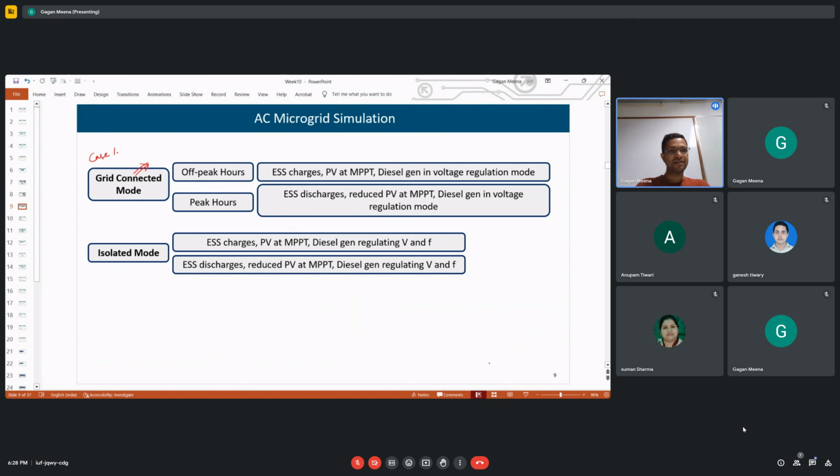Yes. Nice. So DVR, dynamic voltage restorer, D-STATCOM and UPQC. This case study was an example of that UPQC. Here we can see this is one active filter and this is the second active filter. This is the series active filter and this is the shunt active filter. So this series active filter will be used for current related or voltage related problems.